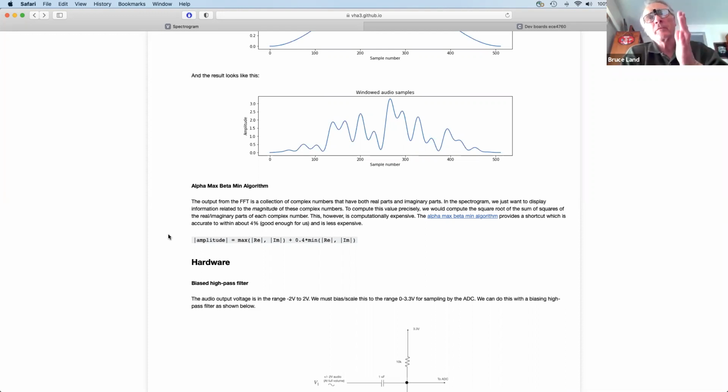Once you get up to the Nyquist frequency, once you get up to n over 2, then you have a reflected version of all of the frequency components in the higher bins, and the reason for that is there's no imaginary component for this signal. Okay. Am I answering what you're asking?